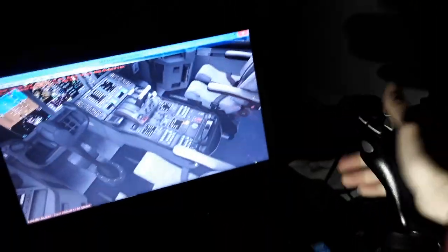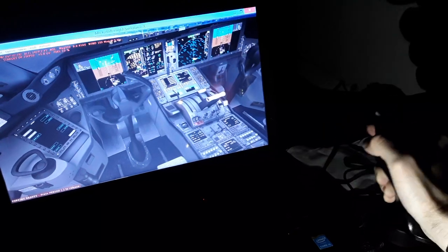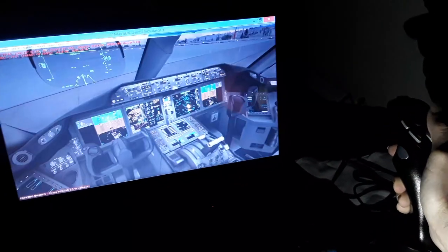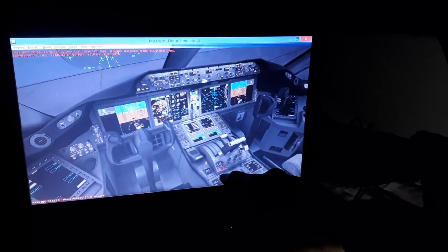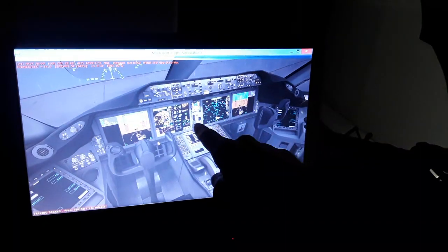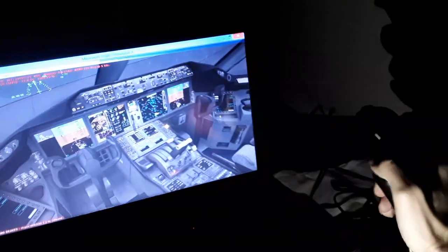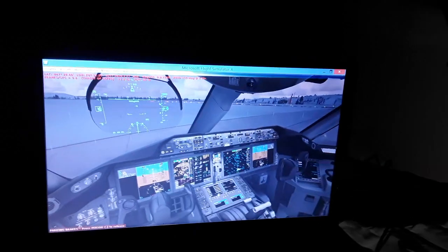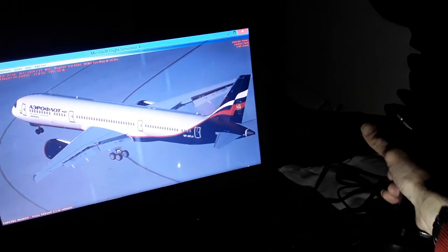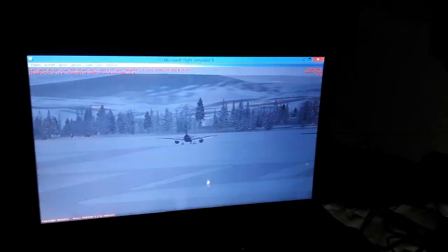So you see the hydraulic systems here, all the flight controls. The elevator, the horizontal tail, vertical tail, the rudder pedals, nose wheel steering, flaps and slats, speed brakes, thrust reversers for the engine, landing gear extend and retract, auto brake, parking brake, nozzle steering here. All these things, the yoke of the Boeing. We need hydraulic fluid pressurization for these flight controls here, so it's pressurized with the engine function with bleed air, and